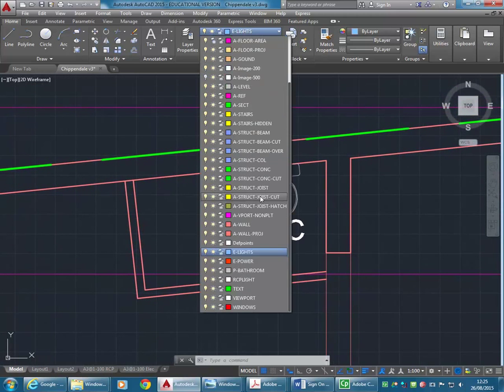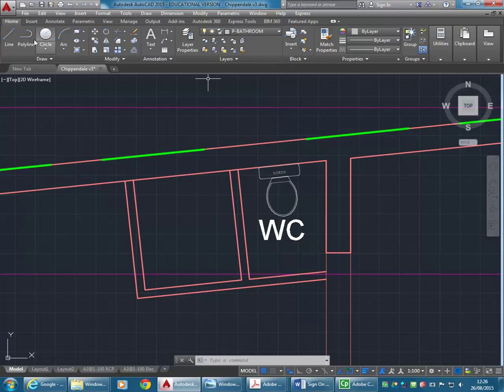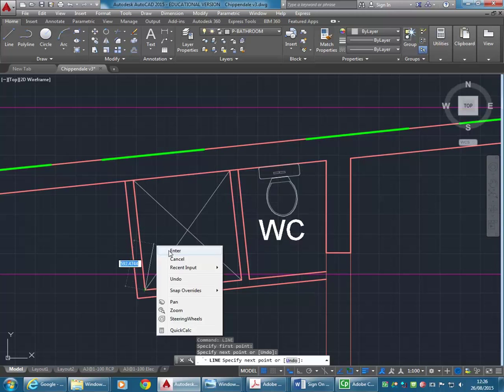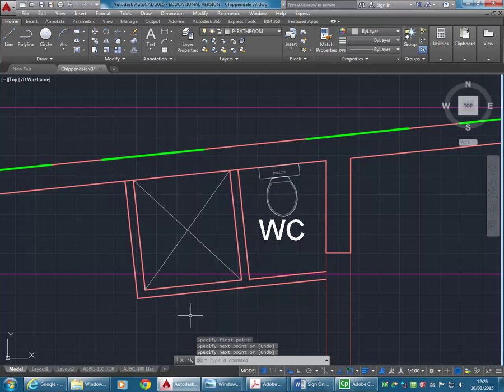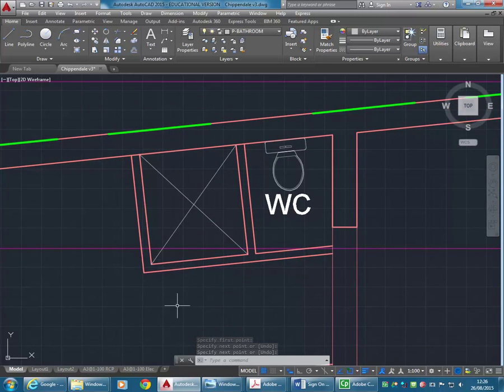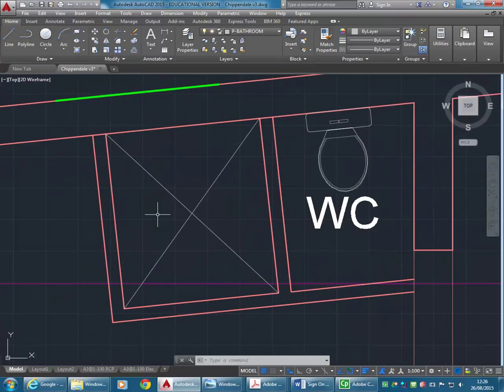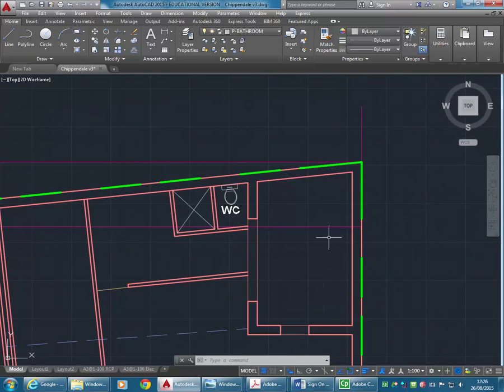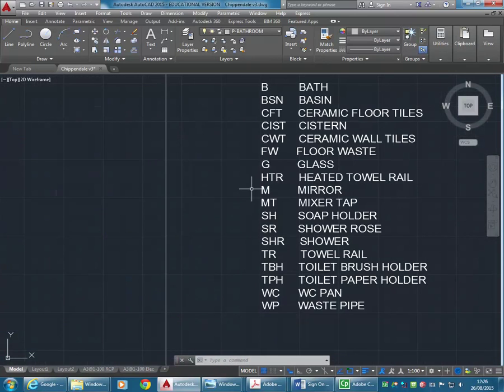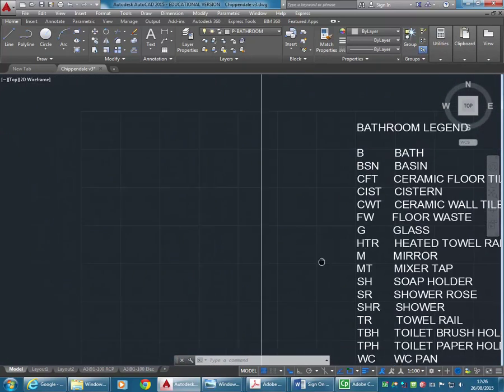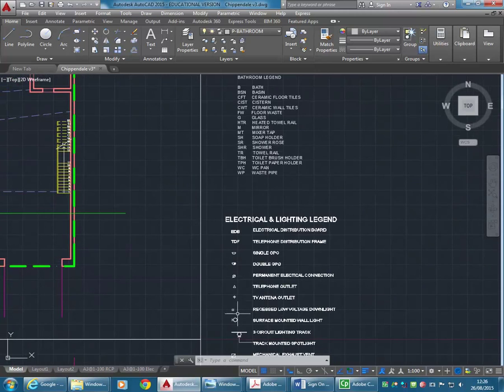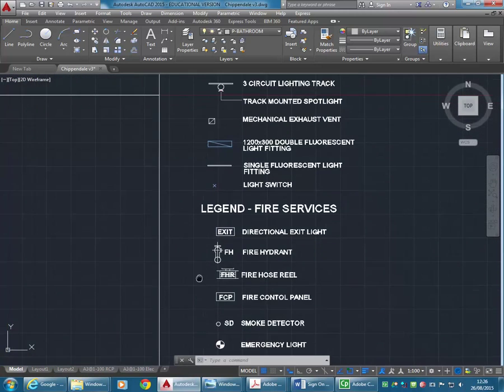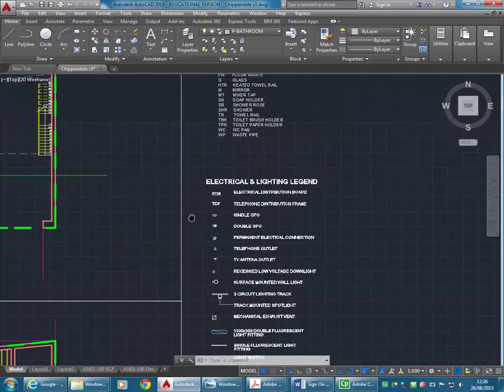And then the shower, it'll have, again, lines just crossing diagonally, and you'll have that open eventually with an opening. So do the tiles after you've done the opening. But you should also show a drain, a floor waste there. And so here FW would be the symbol for that. And there should really be a symbol. If the floor waste symbol isn't here, you can always draw it in.